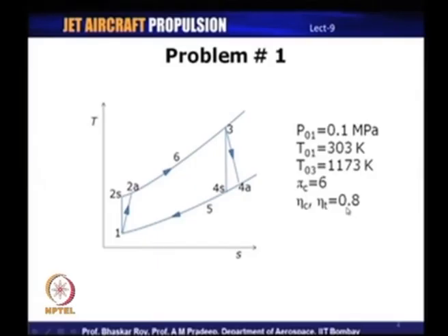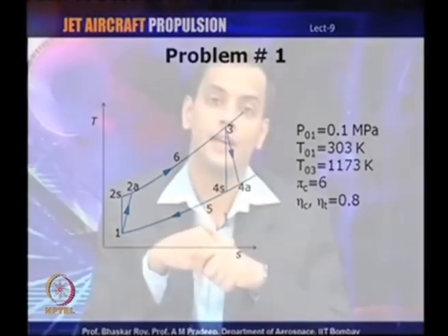So, this is the cycle diagram of a Brayton cycle. Both ideal and real Brayton cycles have been indicated there, something we had discussed in one of our earlier lectures. In this cycle, we know the pressure and temperature at state 1, we know the pressure ratio for the compression and expansion processes, the efficiencies are known, and the maximum cycle temperature is known. And what are we required to find? We are required to basically find the efficiency of this cycle.